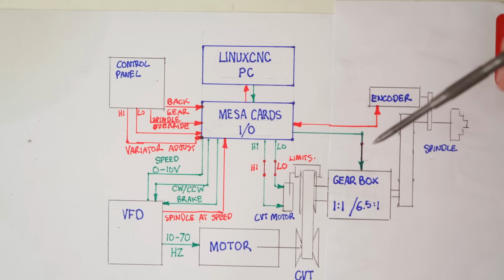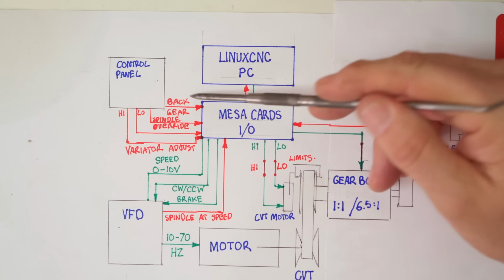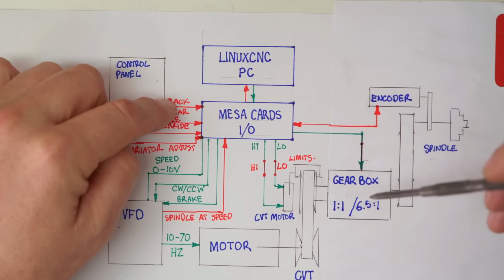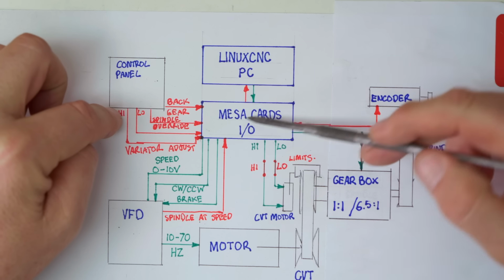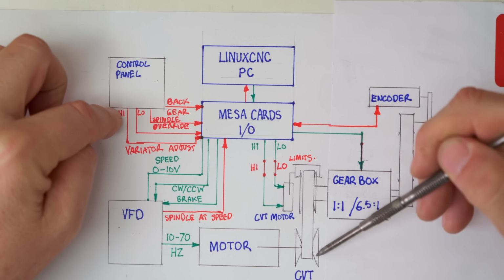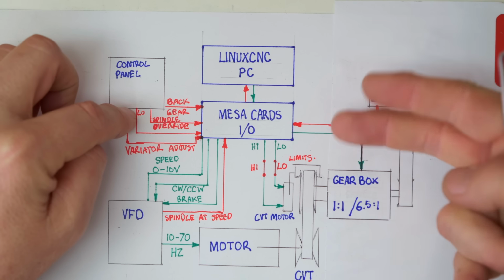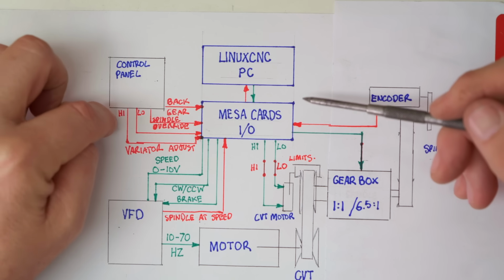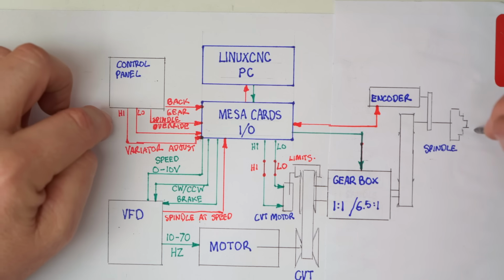So what have I done here? Since I first got the lathe working, I've just been using back gear manually, push the button, change the back gear. I've been manually biasing my constant velocity drive either towards higher speeds or towards lower speeds. The ratios are of course opposite, higher speed, lower ratio, but whenever I say high, I'm talking about high spindle speeds. I'm trying to keep that consistent throughout everything.